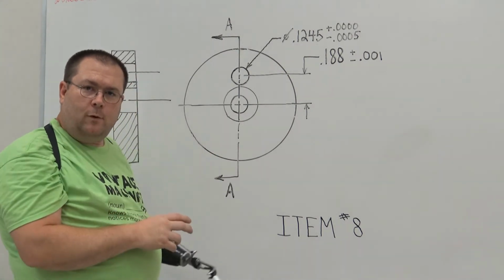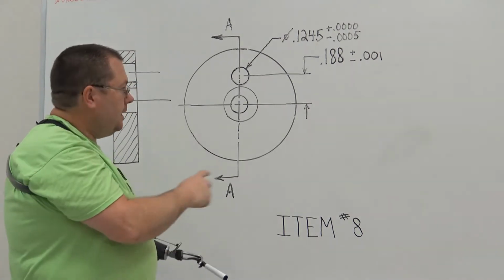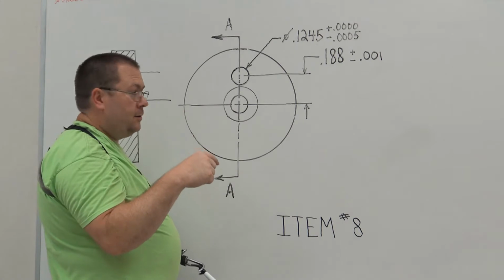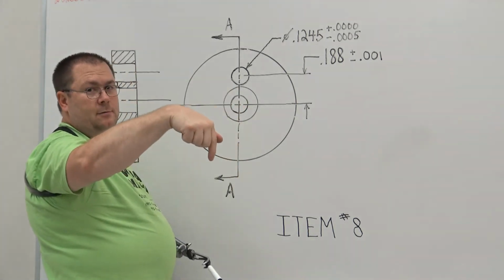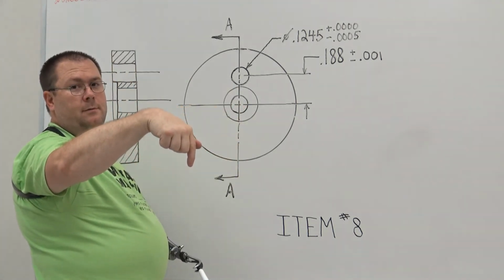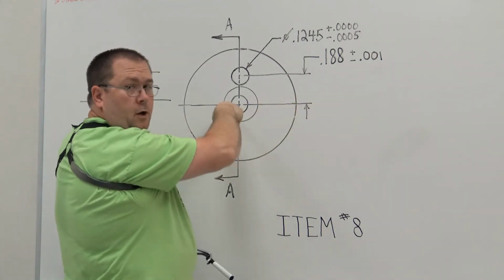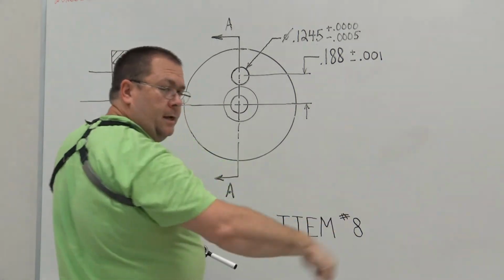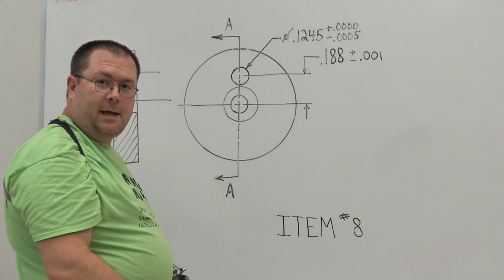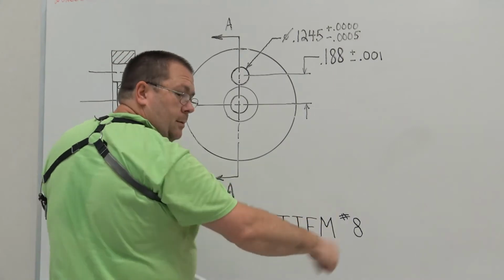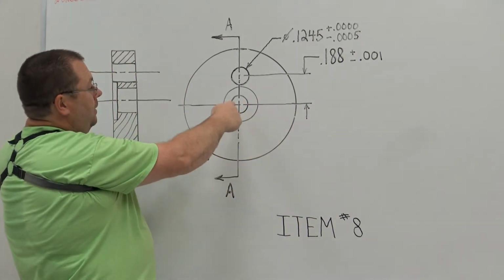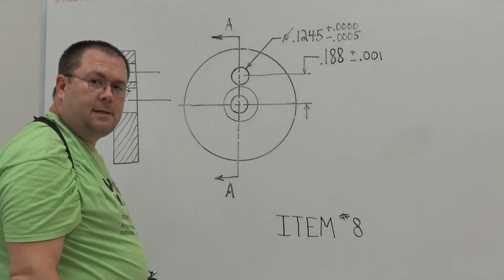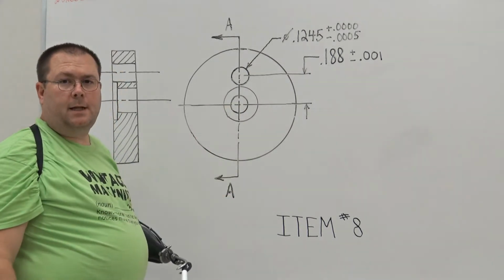So we've got a couple different ways that we can show you how to find that center. First and foremost, we're going to roughly find the center by putting a center drill in your spindle, in your drill chuck, and move it over to the center of the shaft. We're just going to crank it over, use it like an Etch-a-Sketch. Everybody's familiar with one of those. We're going to move the handles around until the center line of the center drill lines up with the center of the rotating assembly. That gets us pretty close.